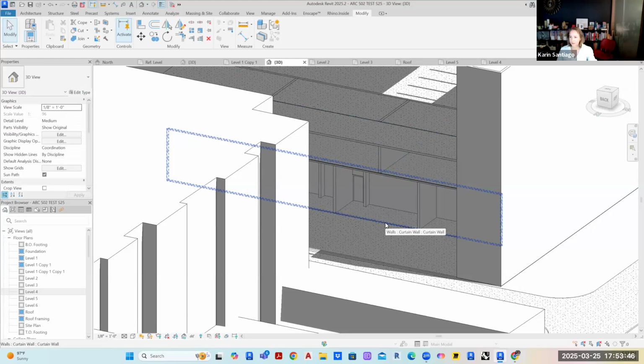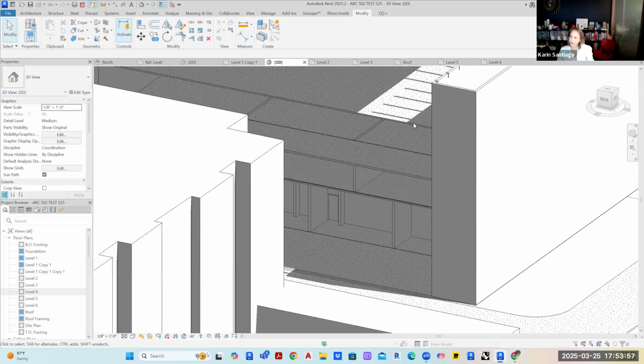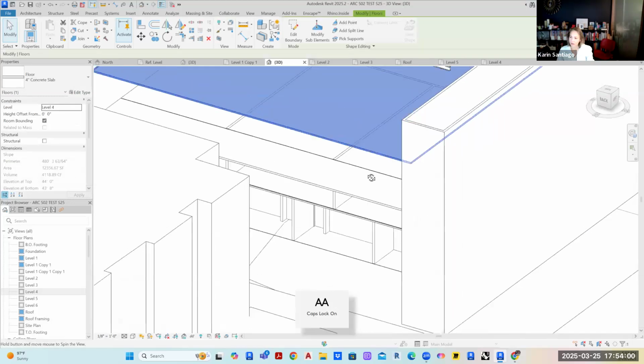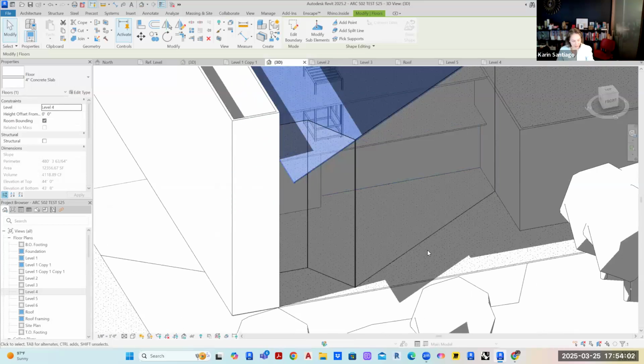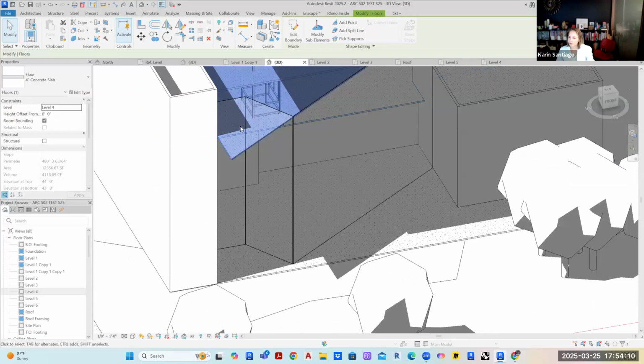And so this is not so much, in proper terms, a curtain wall. It's probably more like glass that sits on its own weight. It's not clipped through the surface, whereas the glass that I have over here, I do think this could probably be more of a curtain wall, which, because the slab edge is so far away, means that I probably will need a structure to support it. So there's going to have to be some kind of structure, more than likely steel behind it, so that I am actually supporting that.